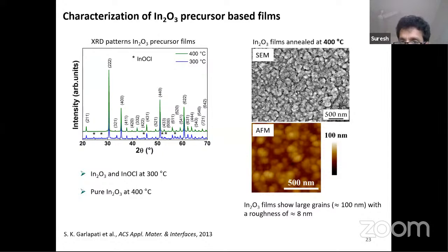They actually lose energy, so they are called inelastic scattered electrons. So you can get different information from backscattered, for example, phase contrast. In case of a secondary electron, you can get morphology. So you can use SEM to understand the morphology and also to understand what kind of composition or the elements are present in the film.